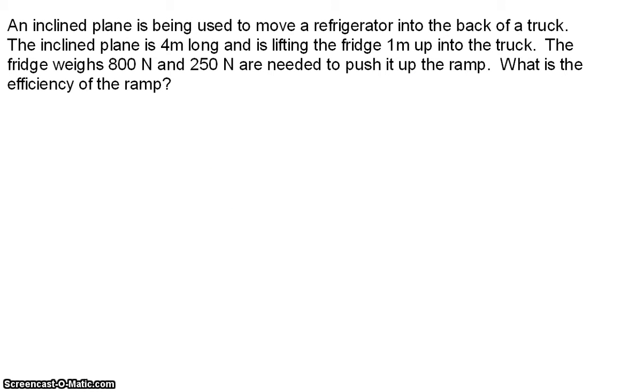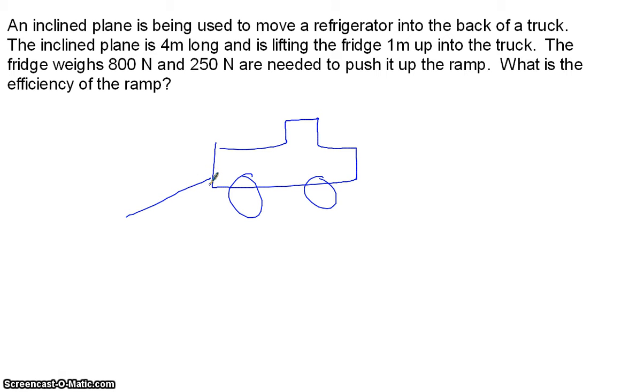An inclined plane is being used to move a refrigerator into the back of a truck. So we've got here's our truck, it has some wheels, it has a plane going into it. The plane is 4 meters long, it lifts up 1 meter in height. We're moving our fridge, which weighs 800 newtons, and it takes 250 newtons to push it into the truck. Okay, so we want to know what is the efficiency of the ramp.